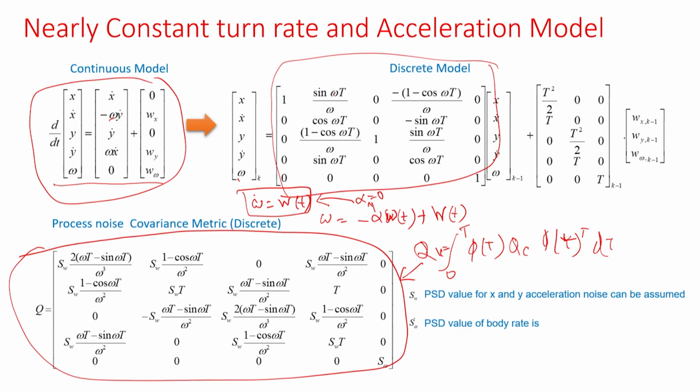One approach is you model it and embed it in your state. Your state dimension will increase. How do you model it? Suppose A11 is unknown. You can model it as A11 dot equal to white noise, or A11k equal to A11(k-1) plus Wk. This is Wiener modeling, with alpha equal to 0. Markov modeling is also okay, but I do not care whichever way you model it.